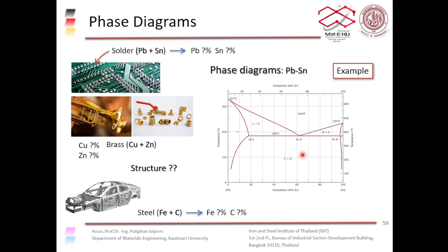Okay, so when you have solid solution, the same as with liquid solution, you have solubility, or the limits that you can dissolve one thing in another. For example, if you want to dissolve sugar in water, you can only dissolve so much sugar in water at room temperature, right? Because you have reached the solubility limits of sugar in water. And if you want to dissolve more sugar in that water, you might have to heat it up.